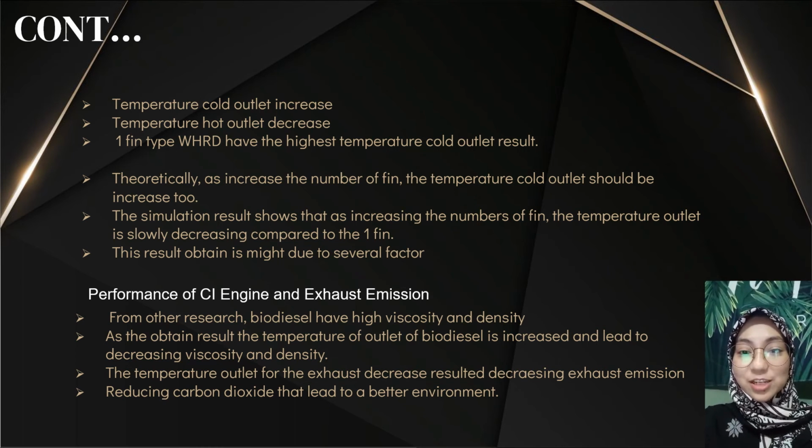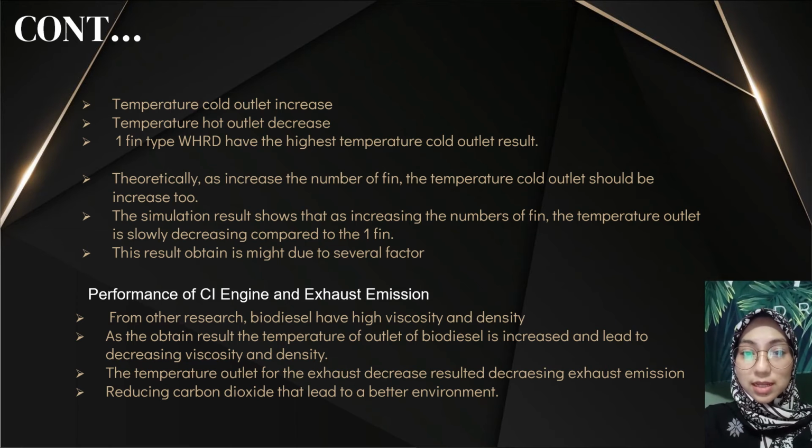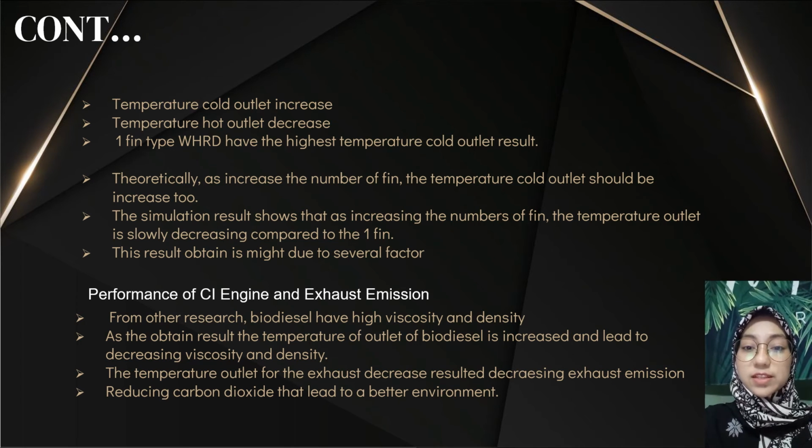Theoretically, as the number of fins increases, the temperature of the cold outlet should increase too. But the simulation result shows that as the number of fins increases, run at 200 iterations, the outlet temperature is slowly decreasing compared to the one fin waste heat recovery device. This might be due to several factors.